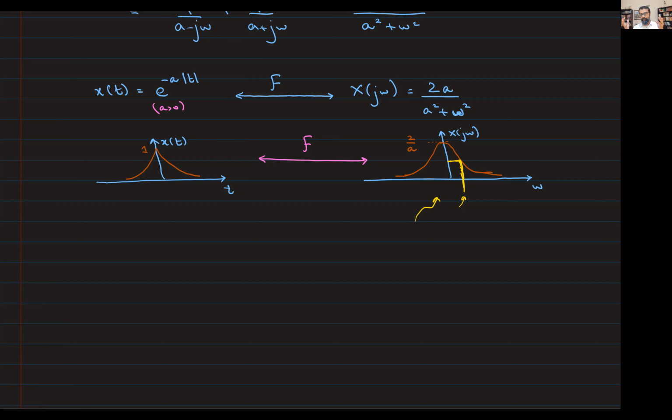So in the practical world, with a speech signal, you can make those connections. What would the Fourier transform applied to a practical signal like speech mean? It means that the speech coming out is actually made up of complex exponentials of different frequencies, and the Fourier transform tells me how much each frequency contributes inside this speech signal, which is more and which is less.